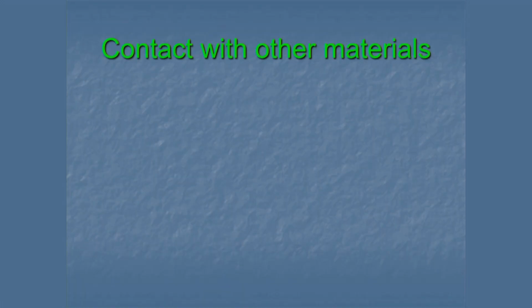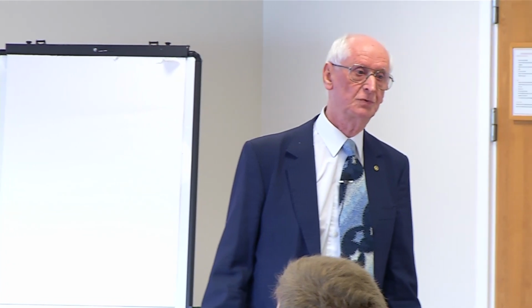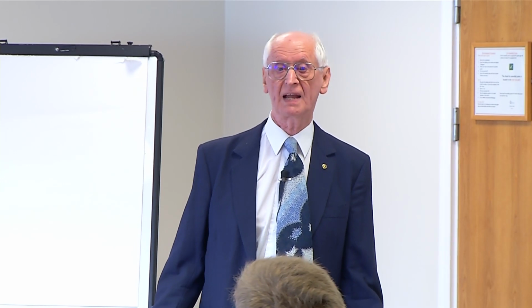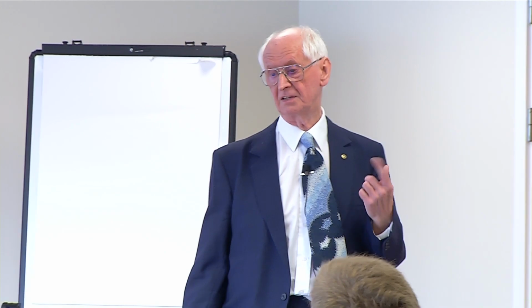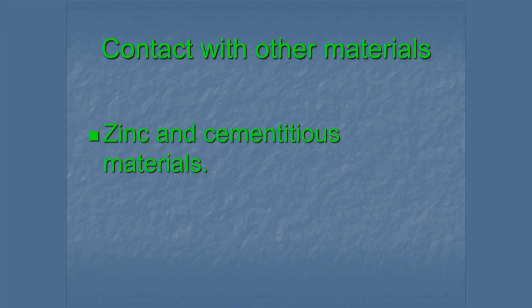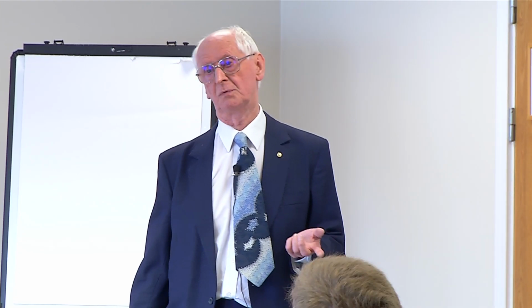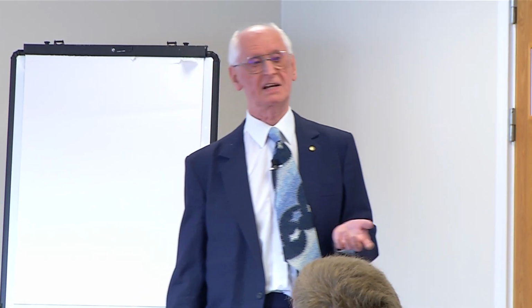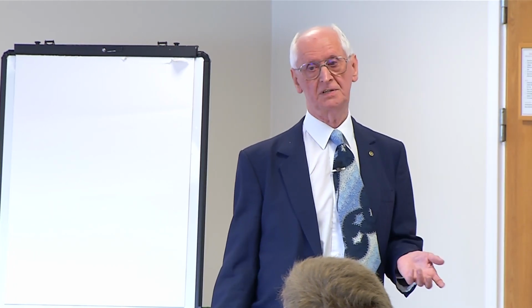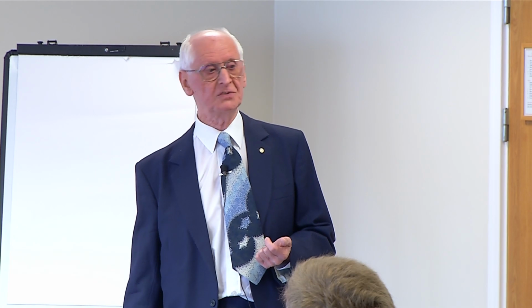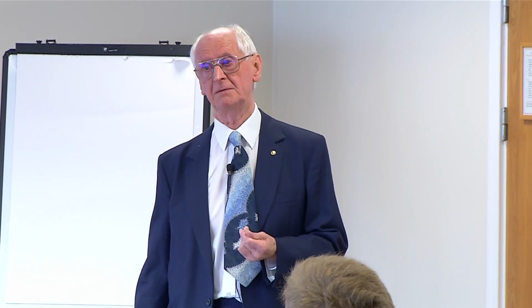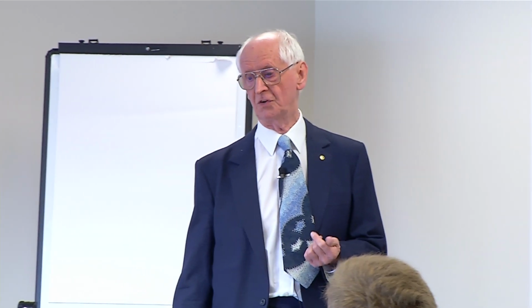In contact with other materials, now this is a particular problem. Some of the materials we use, and the metals we use, react with other metals and other things, particularly zinc and cementitious materials. Now cement is highly alkaline, and in the presence of water it reacts with the zinc and it loses the protection that we actually wanted for it. It happens also with aluminium and other metals. Mixing metals is not a good idea.